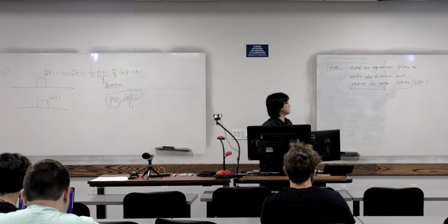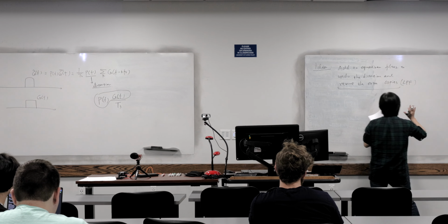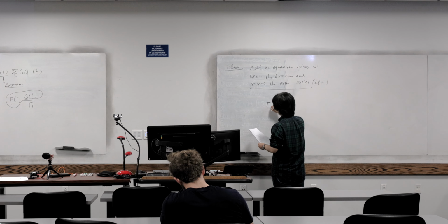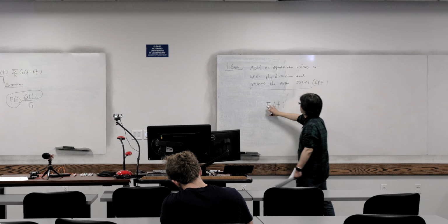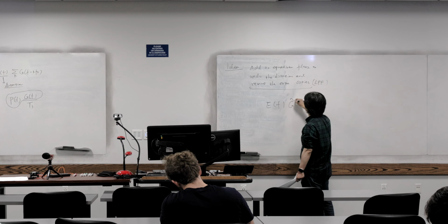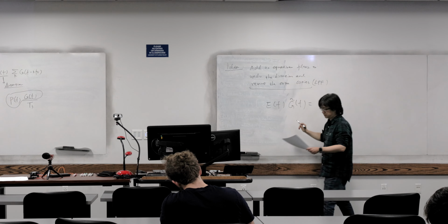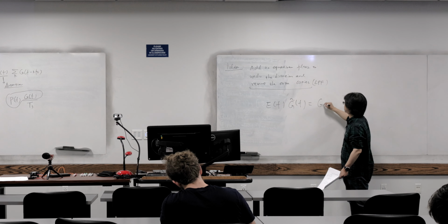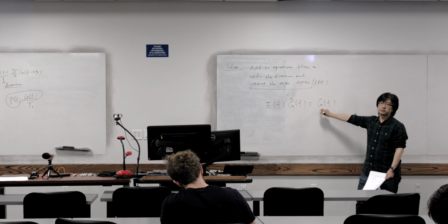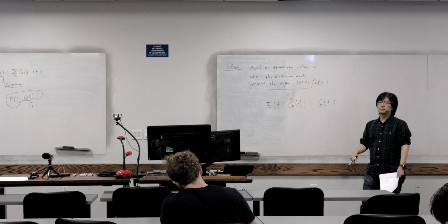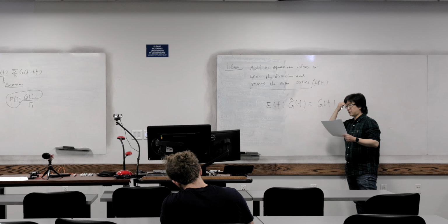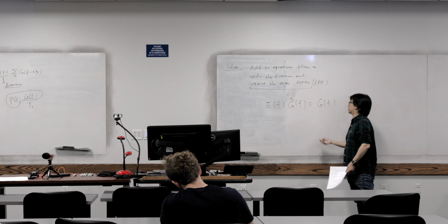So basically, the idea is as follows. Mathematically, what we mean is as follows. We want to design an E(f), the equalizer in the frequency domain, right? This multiplied by G tilde of f has to be equal to G(f), because G(f) is exactly what we want. But in practice, we may want something else, so we may allow a time-shifted version of G(f).